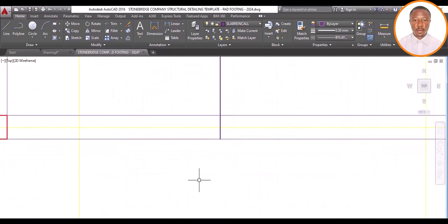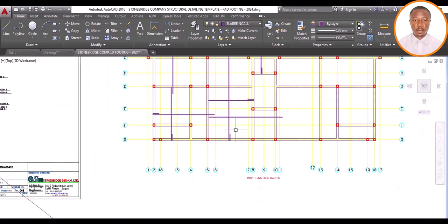So at this point, I bring out my concrete cover, which is 25. Enter. Then pick my line. 100. Sorry, 100. Enter. Then my return bar 600. I've explained how we got 600. Is that okay? So that is that.